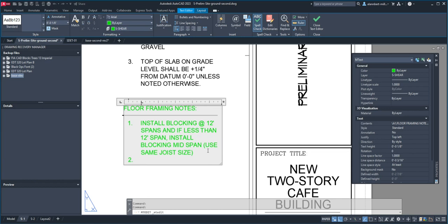Okay. For number two, sheeting. So yeah, we need to also provide sheeting. Sheeting for floors shall be 3/4 inch. Okay. And if you don't want that 3/4, press delete 3/4, and then see this little thing. You can click on that one, and you want to unstack it.